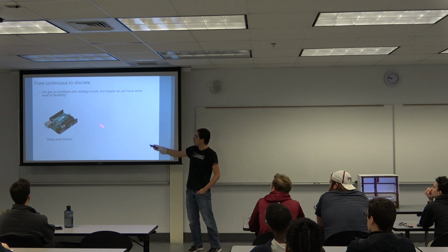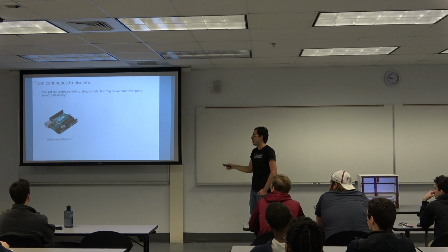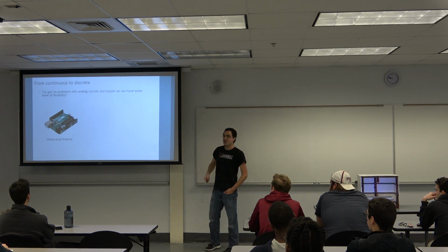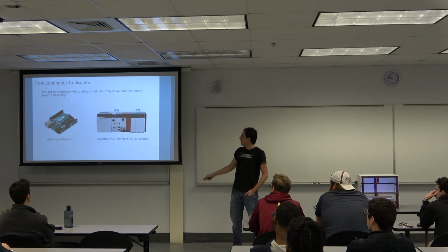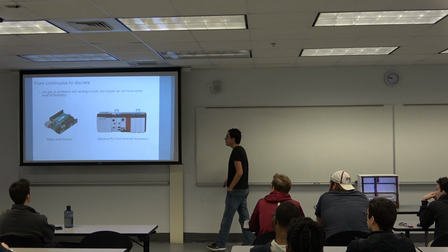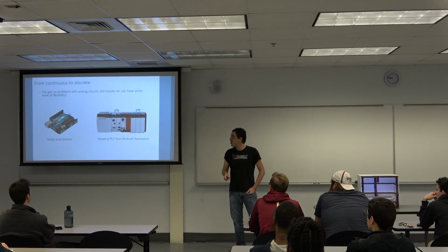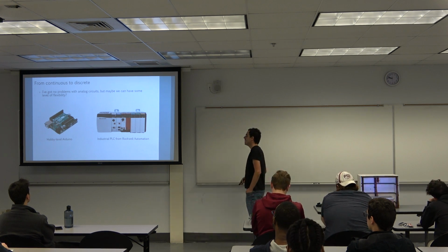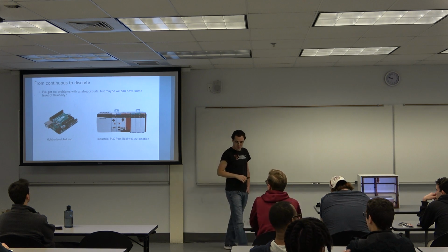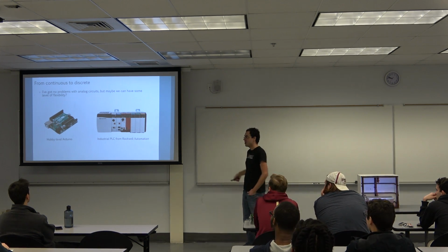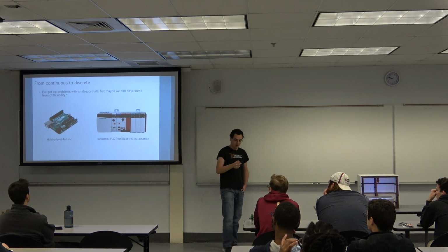So you can implement it in hardware if you're at the hobby level, or you're just doing a student project. You're going to use a hobby Arduino, or a Teensy, or something that is available, and they're pretty powerful nowadays. But if you're in the industry, you're going to need something more robust. So you're going to need a programmable logic controller, which is way more suitable for industrial applications because it has a lot of devices built in to make sure it doesn't fail. It's noise proof, given all the noise in industrial sites and everything.